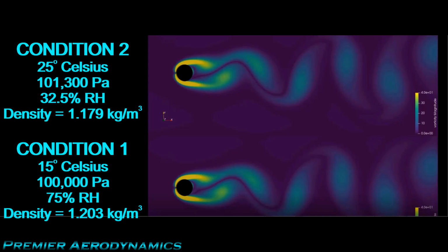Or alternatively, I have a picture here of a couple of cylinders. We'll look at this later actually. This is some simulations that I've done to show you the difference in the flow physics that occurs due to errors in the density. But just now, I can briefly mention, if you have a cylinder and you have an error in the Reynolds number of about 3 or 4%, the Strouhal number will be significantly different, especially in certain Reynolds number ranges. So for example, below about 10,000 Reynolds number and above about 150,000 Reynolds number, the Strouhal numbers really change dramatically with just a small change in Reynolds number.